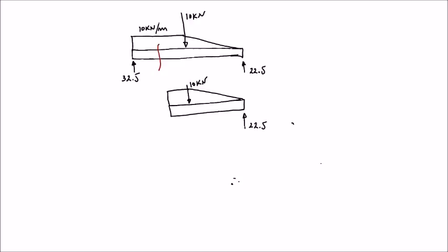And of course, we did cut the beam in this section, and this is my local variable x, starting again at point B and going all the way until the section where we did cut the beam. And again, we need to represent the transverse shear force, Vx, and the bending moment, Mx.